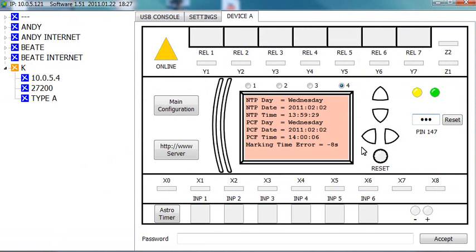The REL1 button also switches on but turns off immediately after the set timeout time, in this example 6 seconds, has passed. Notice that the Y1 light in the main window stays on. This means that the Y1 variable is still active. It will be deactivated when you switch off the INP1 button.